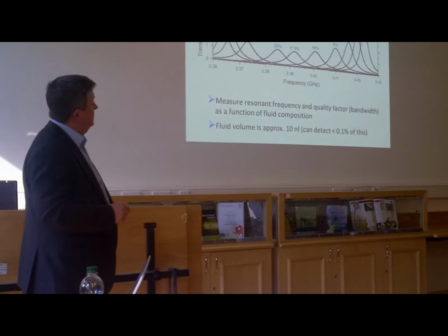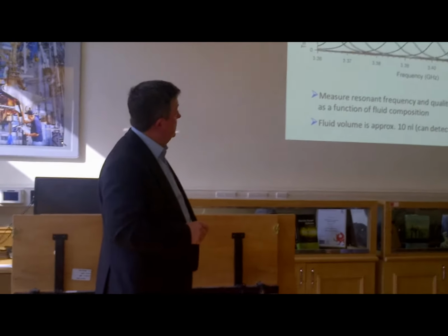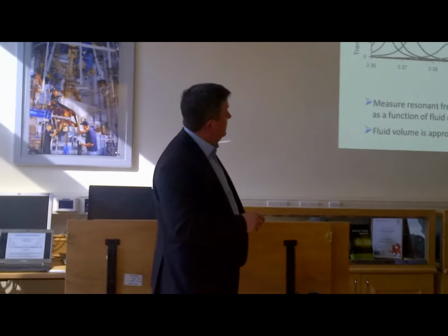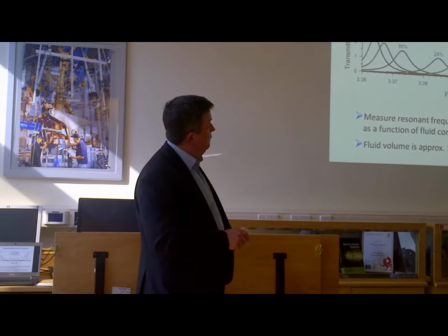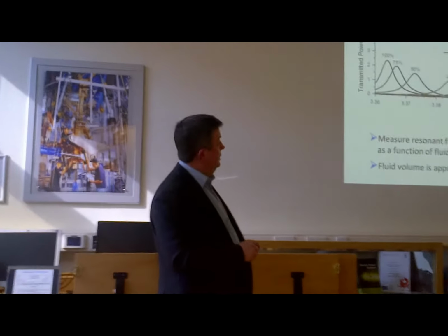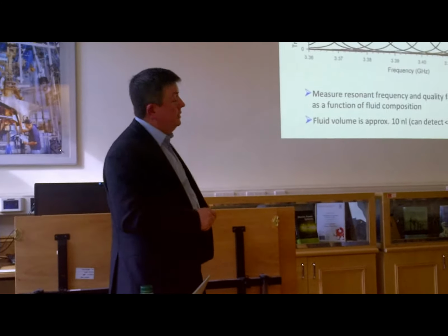The nice thing about this is that this is all happening at one frequency, but if we try another mode, different frequency, we get a different set of curves, and hence what we're doing there is we're looking at broadband dielectric spectroscopy, basically. By looking at different resonant modes, we can then use that to distinguish very carefully between these different types of liquids, indeed different liquid mixtures as well.